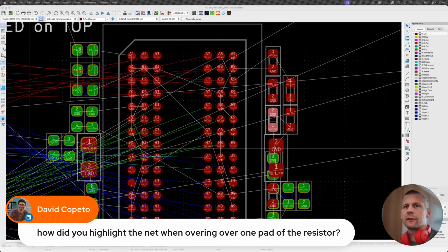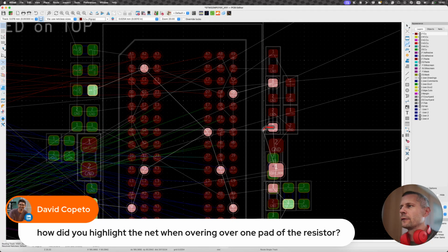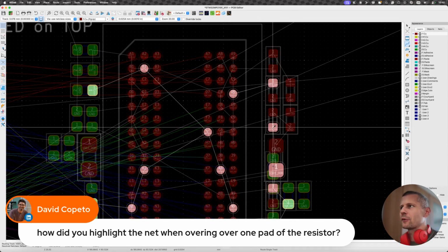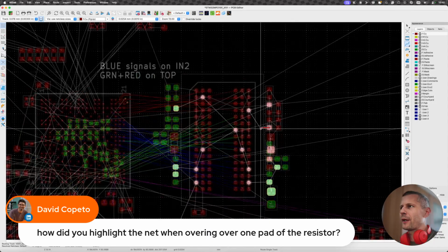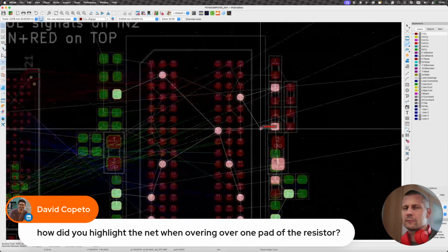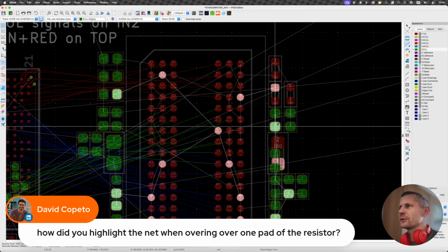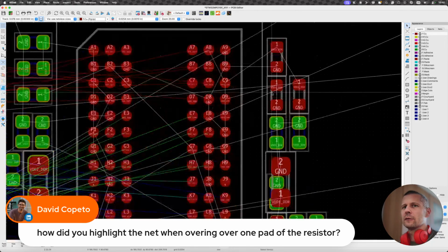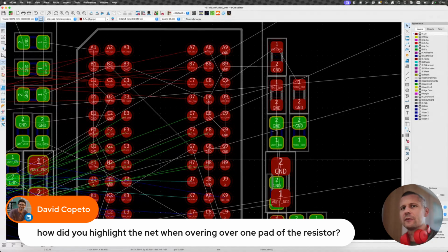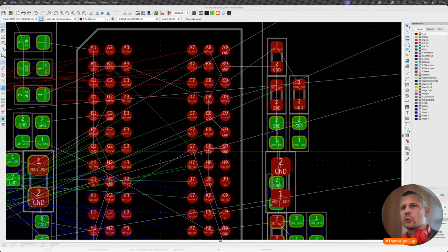Well, I started routing like this. When you hit X to start routing, you can see where the pad signal or track goes to. It's a trick I use to see the distance in between pads, etc. Yeah, just start routing and it will show you.